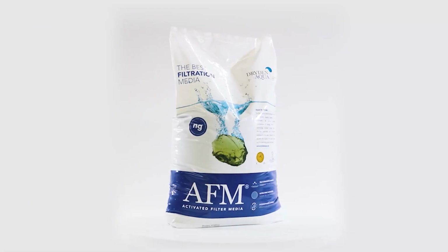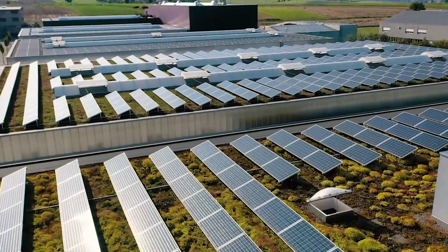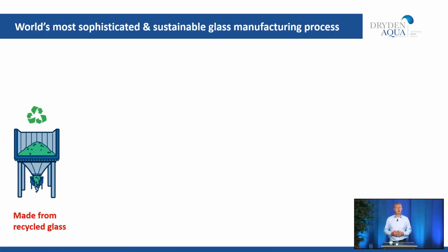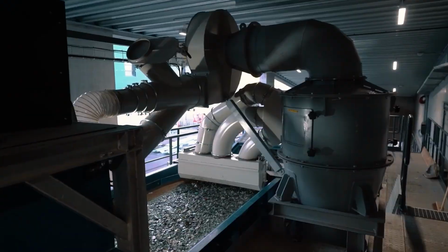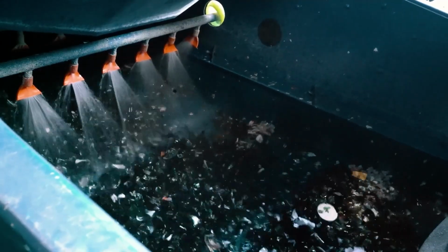How do we produce AFM? Well, it's produced in the world's most sophisticated and sustainable glass manufacturing process. We are literally taking bottles, beer bottles of all sorts, and any glass bottle, into the system from the recycling system. It goes into a hopper at the start of the process. We need to remove the paper labels, the metal enclosures, the non-ferrous materials through a process of magnets, suckers and blowers, plastics as well. We get all manner of stuff coming in with this recycled material. You would be surprised just what we receive.